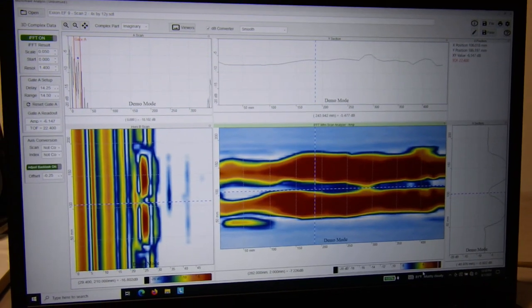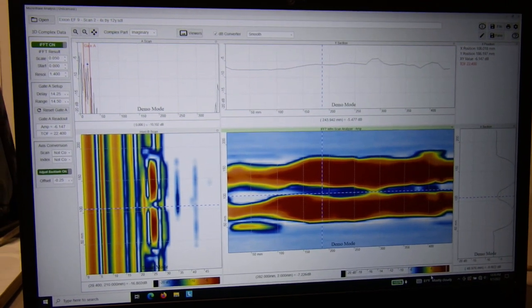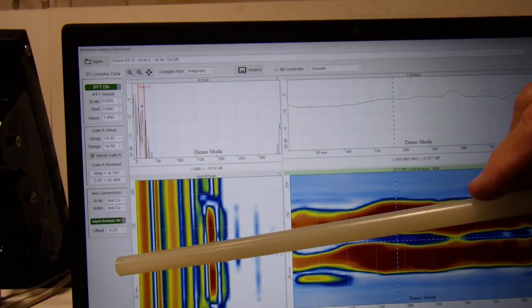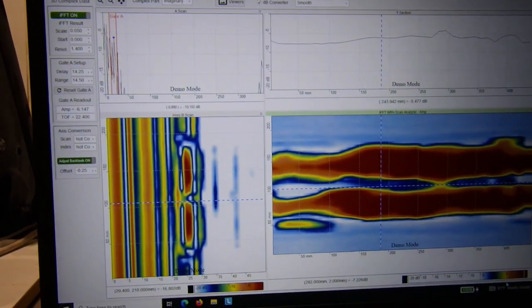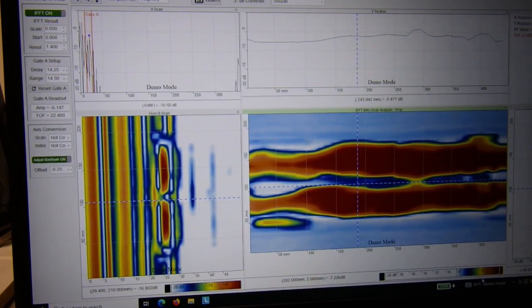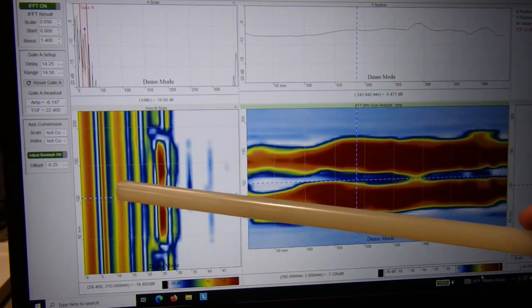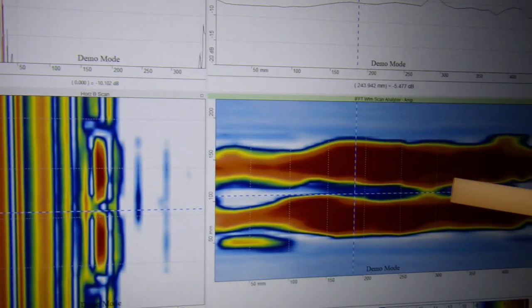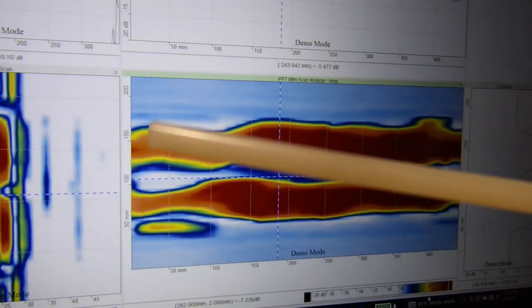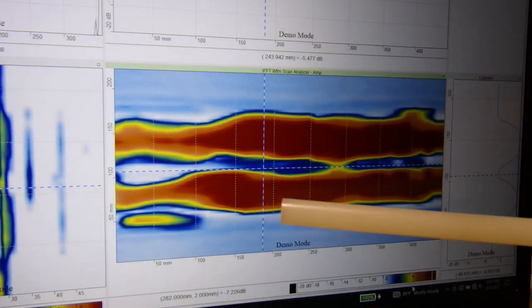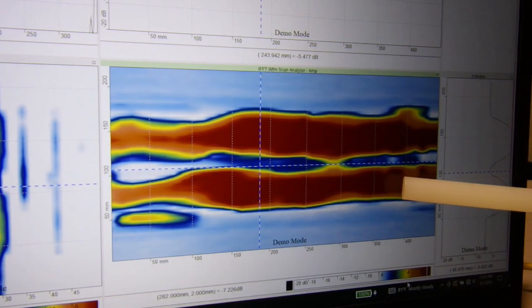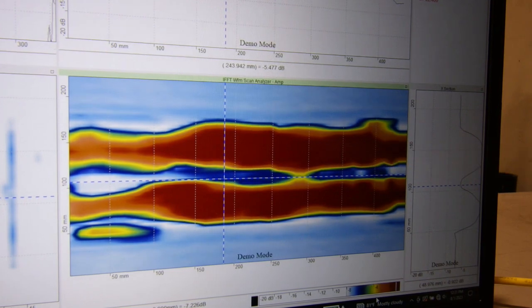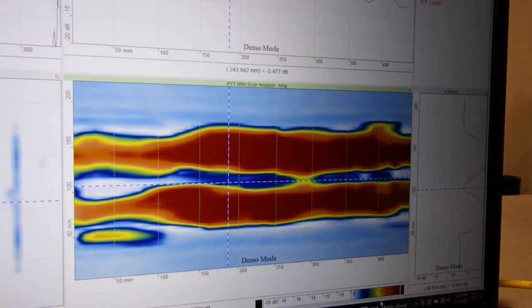This is the second EF joint you provided, EF joint number 9. We're looking at the data from number 9. The left-hand side parameters are very similar as we want to compare equally between the different joints. Again, same thing with the B-scan over here. You can see the area of fusion. And if you go over here to the IFFT view, you can clearly see we've got some issues as the scan began, some variations in width of the fusion, and it appears that we might have some spacing problems between the ends of the pipe before the fusion was made.